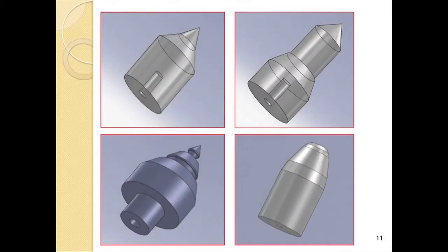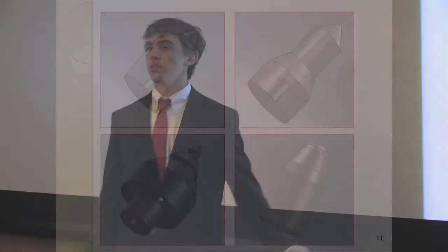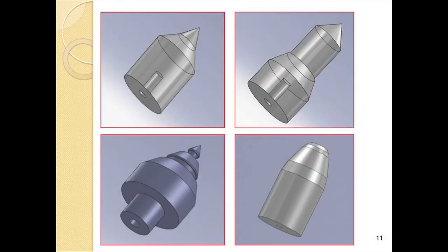These are the four original models that we designed. The first in the upper left is a double cone. We expected 2 attached shocks for that model. The bottom left is the ridged cone. This is one that we designed not quite sure what would happen, but expecting that we would see attached shocks at each of the ridges and at the point in front. The upper right is the cone cylinder with flare. We expected all attached shocks there as well. These all have different angles at their front face, so that we'd be able to test different parts of the NACA table shown before. And then the bottom right was my model, and that was a blunt model. So we wanted to see how far off the detached shock would form from the front face of the model.